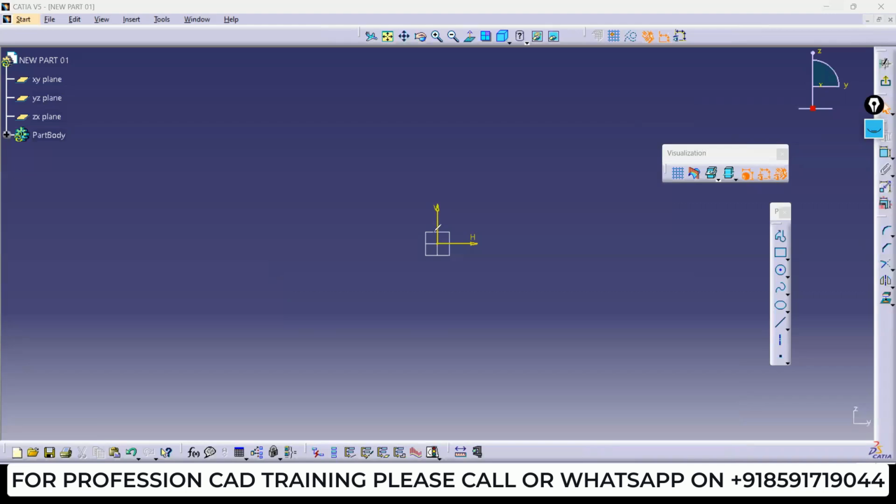The workspace has changed, right? Now you can see only two axes, vertical and horizontal, which means you have now shifted into 2D. A sketch is represented in 2D, whatever is in our mind we represent on paper in 2D manner. So 2D we need to create first, a two-dimensional view, and then we can apply material to create it three-dimensional, right? If you go to the part body now, below the part body you can see the sketch is added.